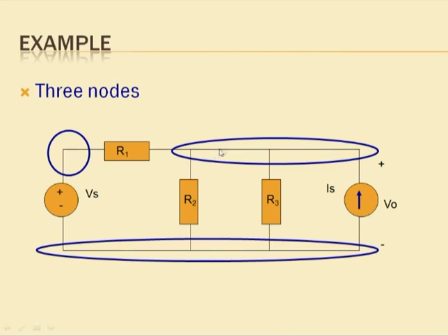So if we neglect the resistance of that connecting wire, then we can consider this point and this point both same. So what it means now, earlier as we thought that the R1 and R2 are connected at this point. Now you can say that the R1, R2 and R3, all these three resistances are connected at this point. Again, we can correct our answer because the IS is also connected with the same point.